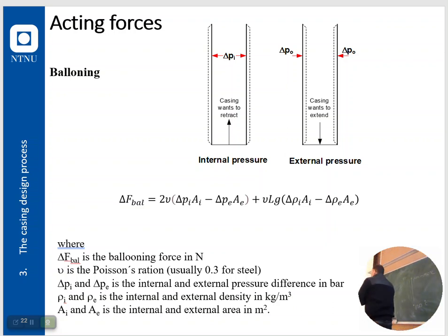Now, any load case that we set up is a combination of all the forces that we are talking about now. Now we are dissecting the load case, any of them, and we say that yes, there is bending on our pipe, and that is how we adapt pipe. There's at one point some ballooning when you're pressure testing. That's included in the load case, and thermal changes. That's included. Everything is included.